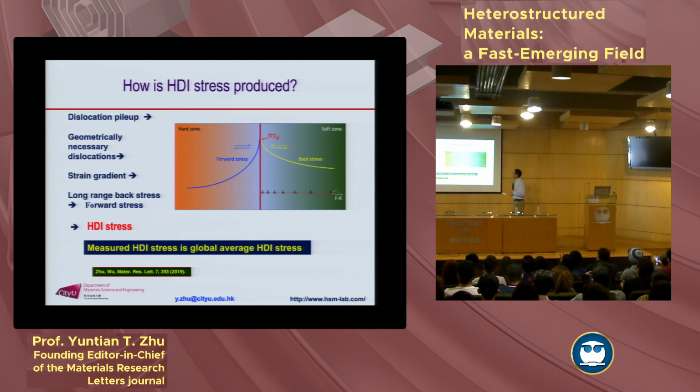On the other hand, also look at our textbook, you have dislocation pile-up at the pile-up head, and here you have a stress concentration. How much is the concentration? It is equal to N tau A. Tau A is the applied stress, what you applied externally, multiplied by N here.